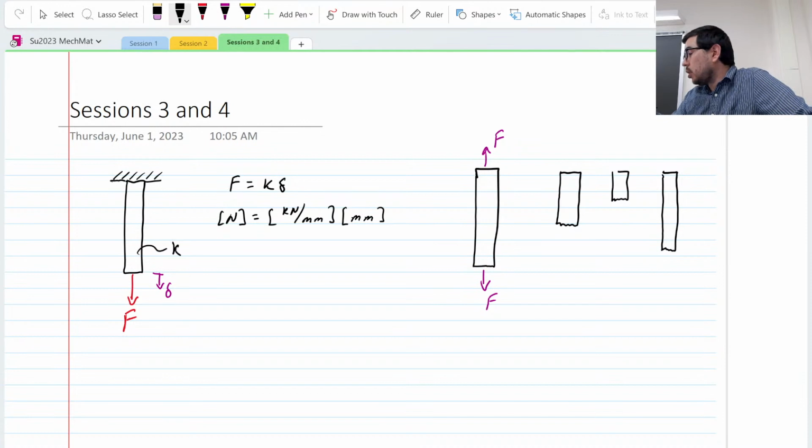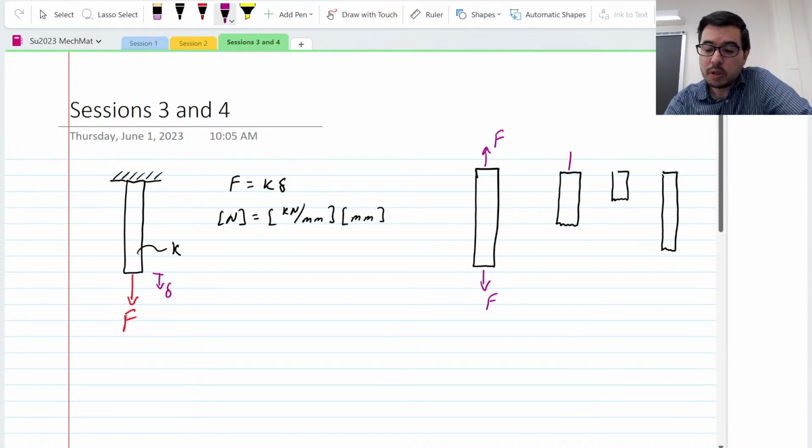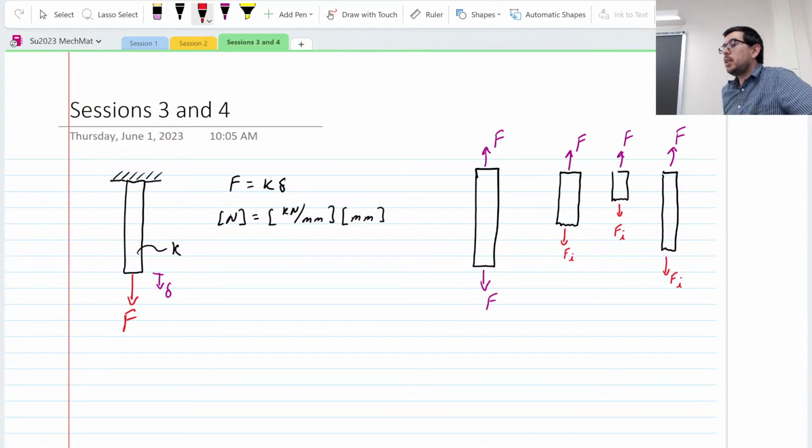and it's not like a distributed force, which you're familiar with from statics, being applied along it, if there's no reaction force, no constraint, nothing applied along it, then the force inside, that internal force, is just going to be exactly the same. Now you're like, okay, that's kind of silly that I'm making this point. Why am I making this point?